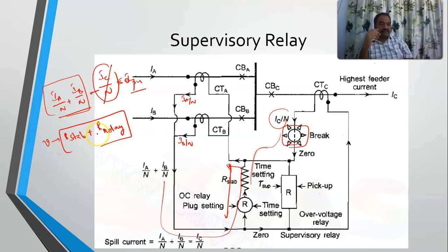Because there is a current flowing in the circuit, isn't it? Now if you are able to identify that there is a voltage being developed across these two points, and it is greater than your small value, then automatically it means that some of the currents are not flowing in the circuits, which means that it's an indication that there is an open circuit, isn't it?